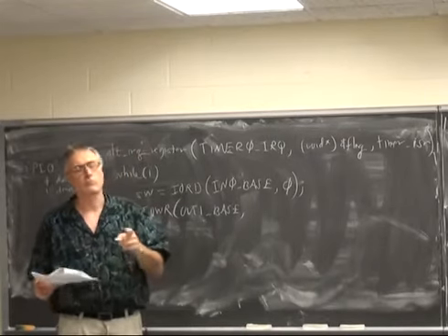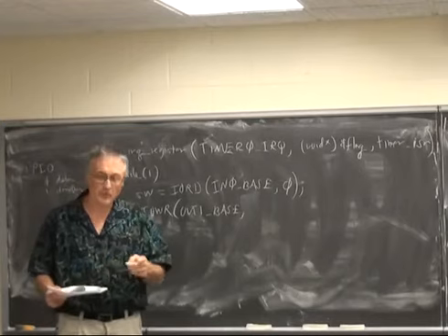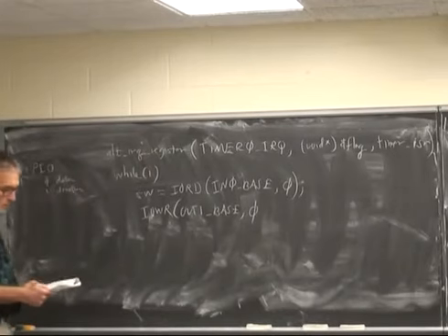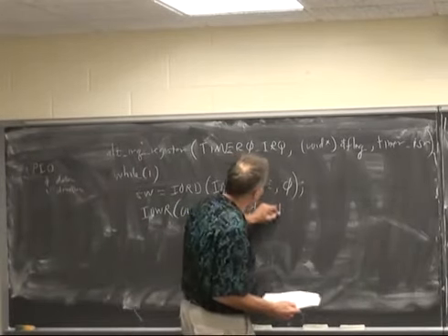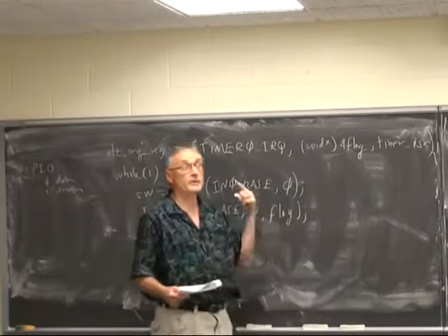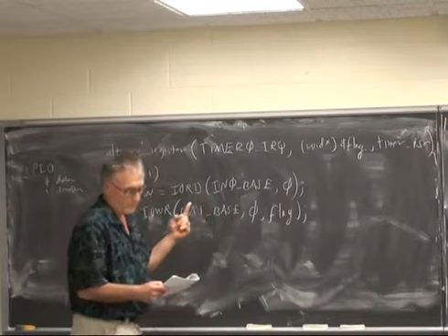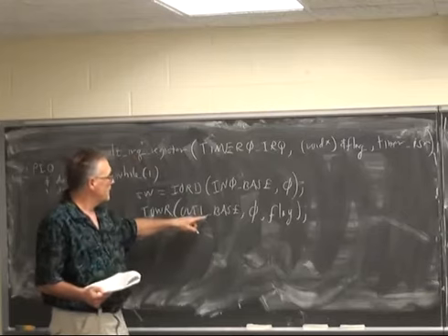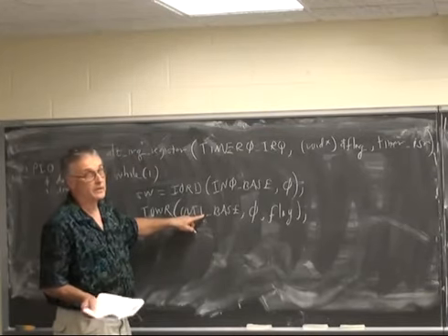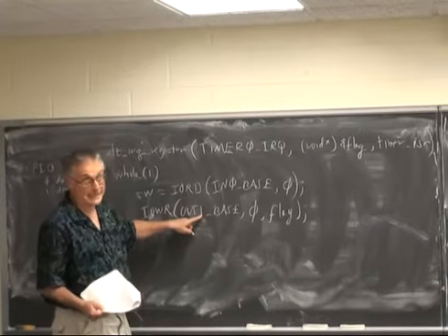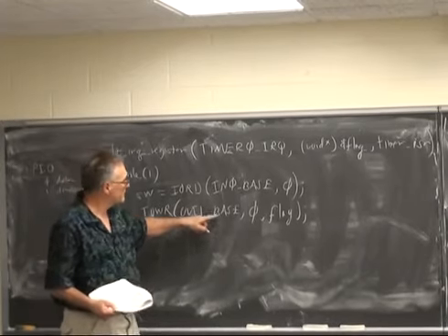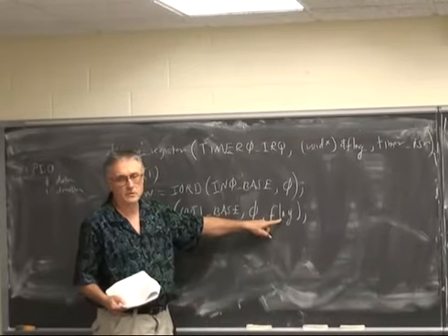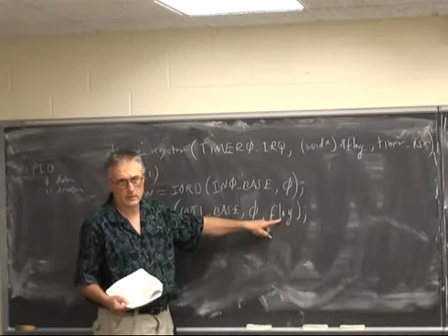For an IO port, you write to the same port that you read from, so the output data goes to offset 0, and we're going to output the flag, which is being updated in the interrupt service routine, so that the device which is connected to the OUT1_BASE, the green LEDs, red LEDs, will just indicate the binary equivalent of the flag variable, which goes from 0 to 8.